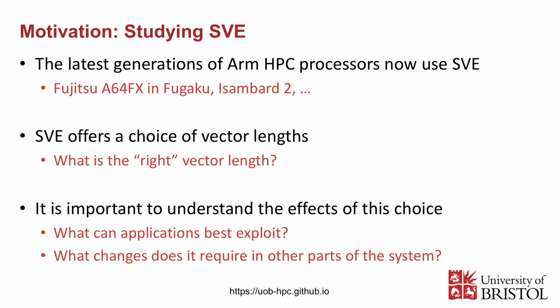One of the interesting aspects of SVE is that it presents a novel research problem. Because vector length isn't fixed, but rather each implementation can choose its own, how do we choose the best vector length for future hardware? We've been looking at this from two perspectives. One, how well can applications take advantage of SVE at various vector lengths? And two, how does this choice interact with choices made in designing other parts of the chips?